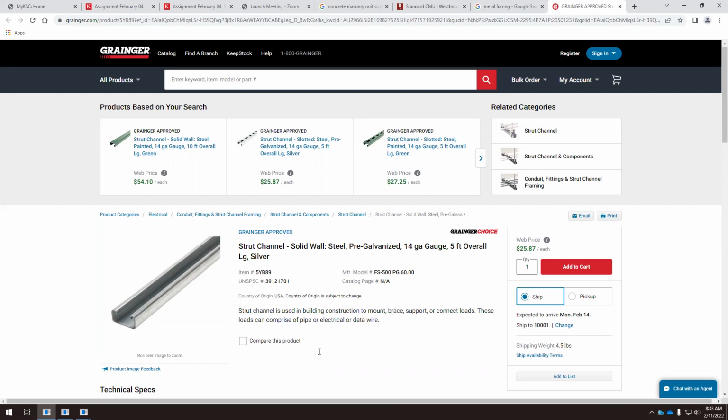And here we have these elements that are attached to this and are holding the gypsum board. Okay, but this is air, and this is air. So in this section, we don't see this element, but in the plan, we would see this element. Okay, so this is what the metal furring means.